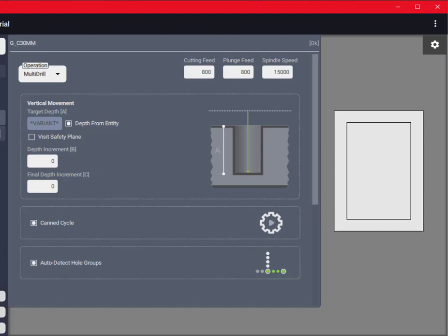Nevertheless, I would like to emphasize that this checkbox allows adekoCAM to check if there are multiple holes suitable for concurrent drilling in case the machine is capable of drilling multiple holes at once. It groups the suitable holes, if any, and finally performs the action with highest possible efficiency. If the machine has a boring head, this operation saves quite a significant time during manufacturing.